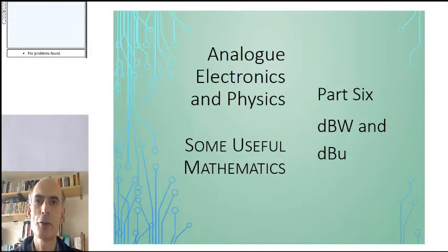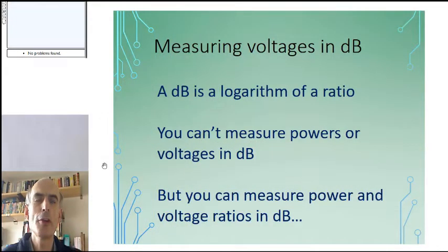Hello, welcome to part 6, in which we'll be looking at some methods to express voltages and powers in decibel terms. First thing to note is that a dB, as we've just seen, is the logarithm of a ratio, and therefore you cannot measure voltages or powers in dBs because a voltage or a power is not a ratio.